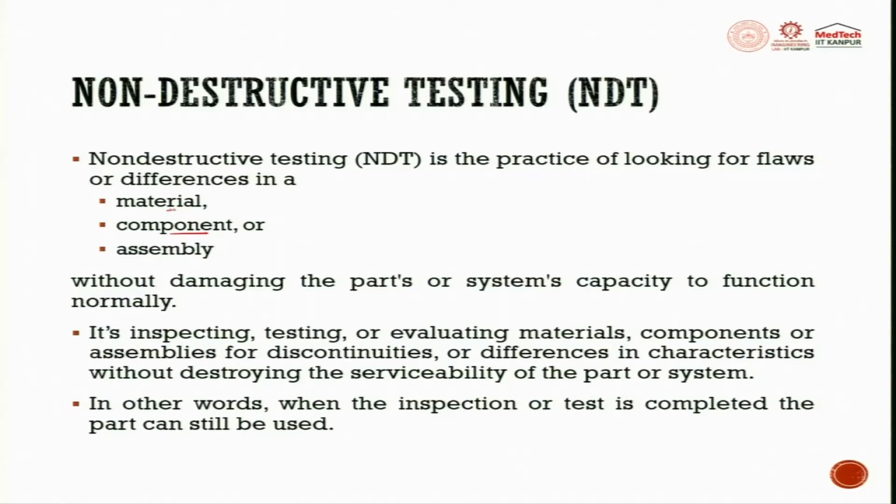Now, non-destructive testing as a definition is a practice of looking for flaws or differences in a material or a component or an assembly without damaging the part's or system's capacity to function normally. So, it is a process of inspecting, testing, evaluating the components, assembly, materials for any discontinuities without destroying, without putting any harm to the component. So, when the inspection test is completed, the part can still be used.